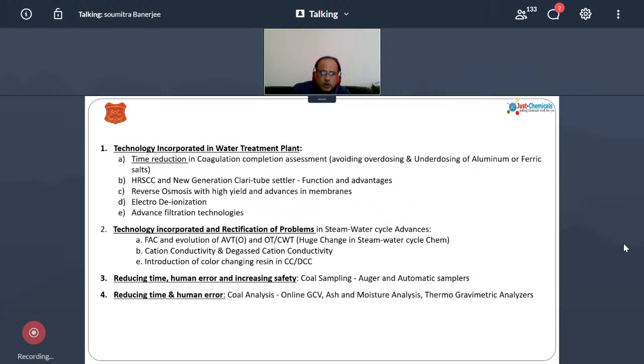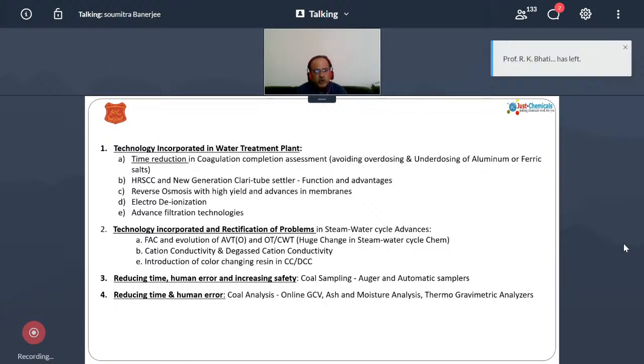We'll also talk about the technology incorporated in rectification of problems in the steam water cycle. FAC is flow accelerated corrosion. Though FAC has been recognized a bit late in India, ultimately it has been recognized, and the evolution of AVT and oxygenated treatment started in Germany, Japan, and the US quite earlier than us, but we have understood corrosion.